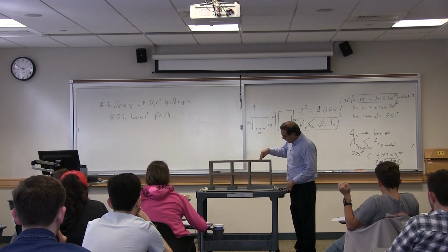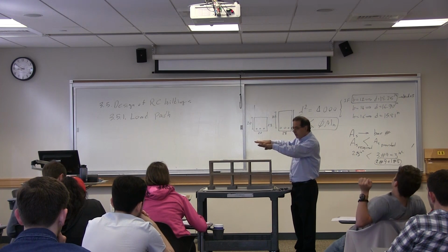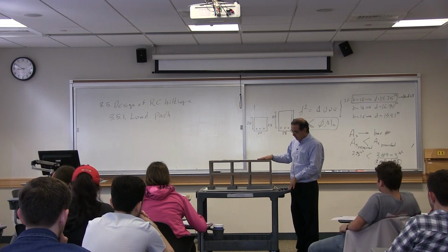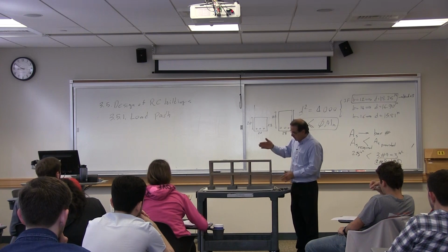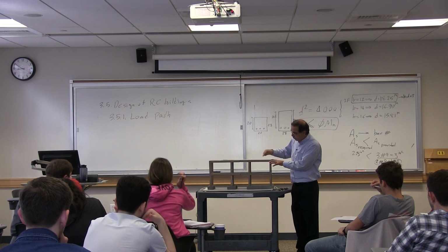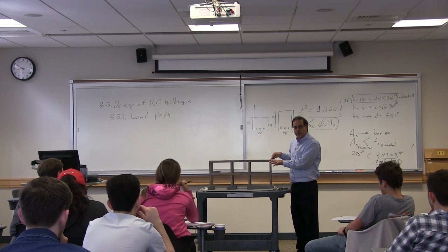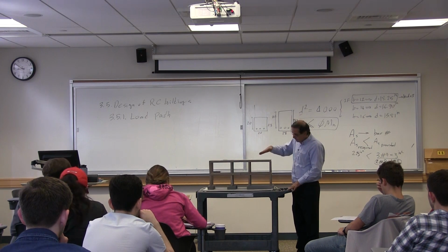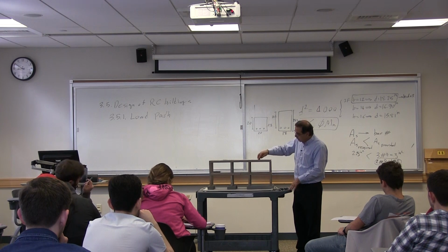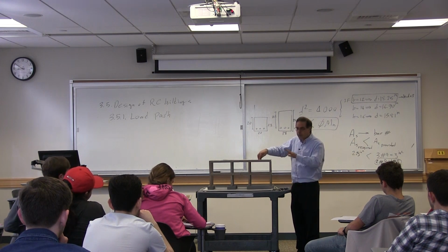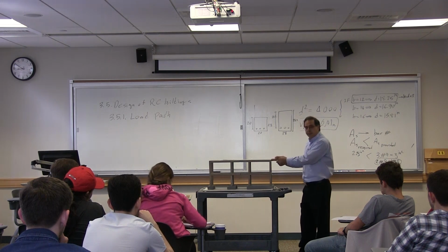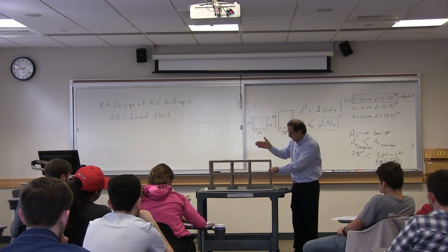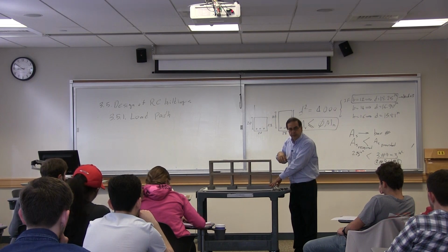I apply load here, the slab would deform. Depending on the shape of the slab, which we'll talk about maybe later today, loads would transfer more to these longer beams, not to the shorter beams. Therefore, in this building, or in this model, the load applied here will go more to these beams than to these beams. From these beams, we'll go to these columns in this direction and then go down to the footing.